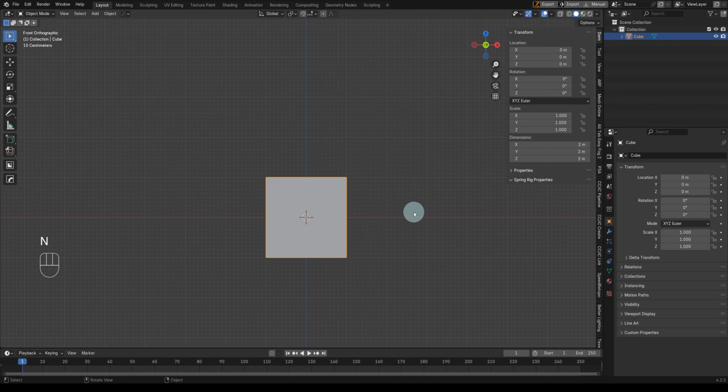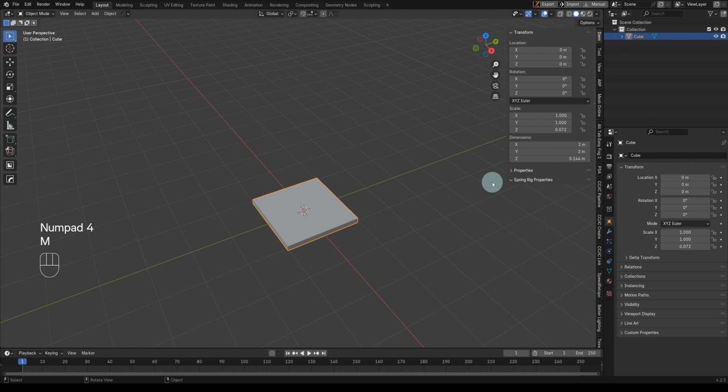And then while in Blender, I'll press N, go to the N menu, and then my dimensions. I have Z to be 144 mm. I have Y to be 28, but I'm going to use 30 mm. And then I have my X to be 70 mm. Now Blender converted from meters to millimeters automatically. All you have to do is know your figure and then know the SI unit of what you're converting to, and voila, you have that.